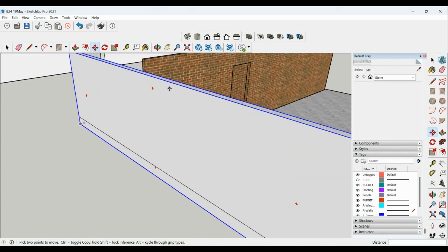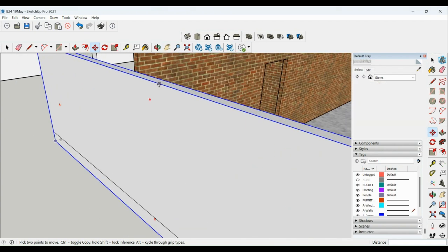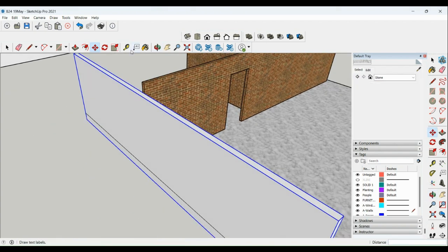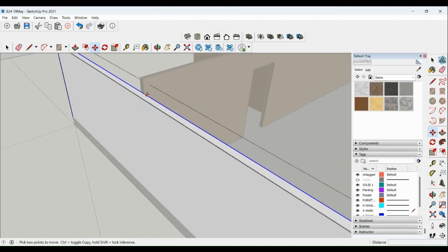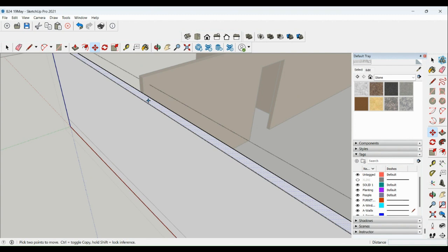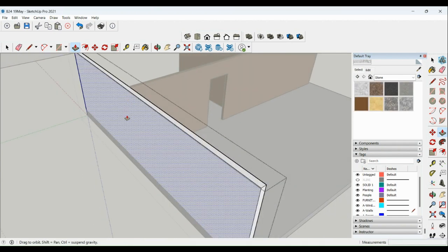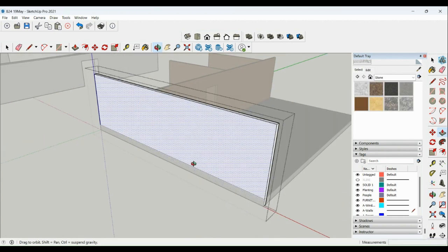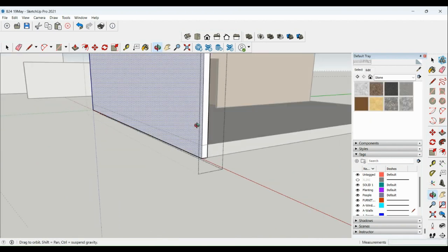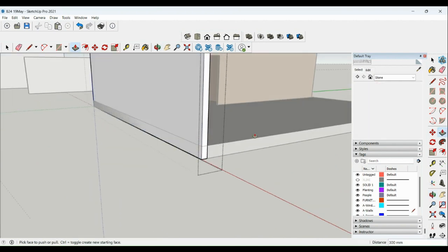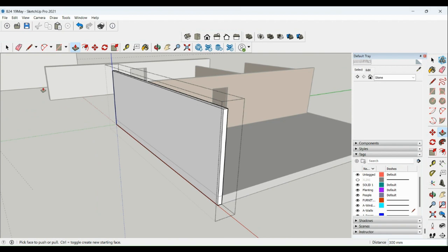And then later on I can edit the group and adjust the height of this. Can make it another 300. So that will be the height, so it's in the same height. So now I think I can cut this and it will deduct that floor.